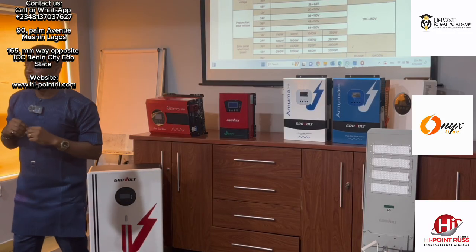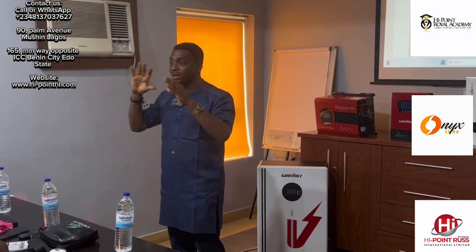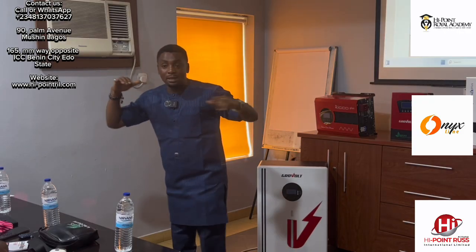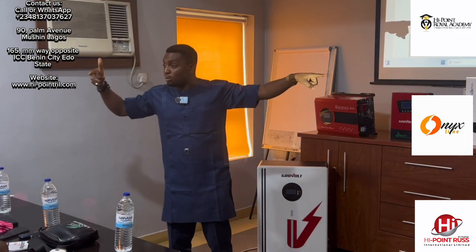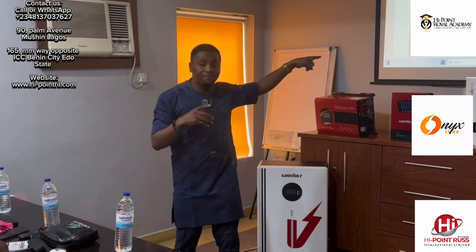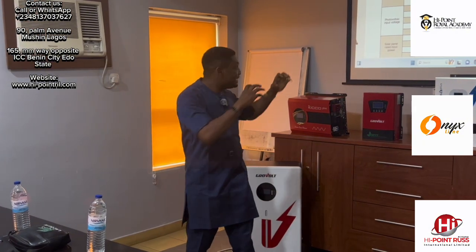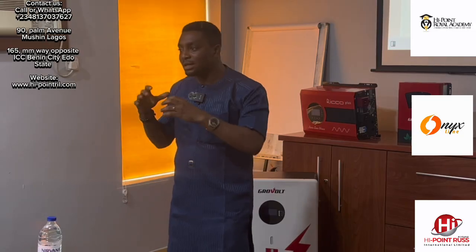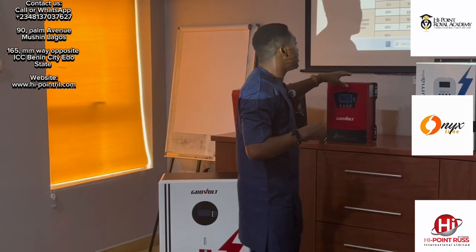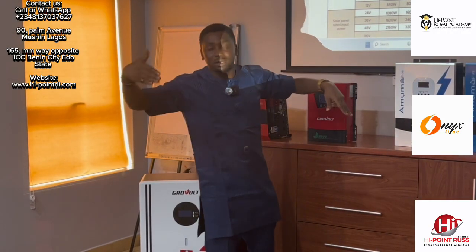The reason for this is that during a cloudy period, when the weather is very unfriendly, and you have enough solar array, because it can accommodate double, it will still operate optimally. You can still get around that 540 watts even during a cloudy period. During intense sunlight it takes that 540, and during a cloudy period it can even take more. This is the beauty of this charge controller, and it's also applicable to 24 volt, 36 volt and 48 volt systems.